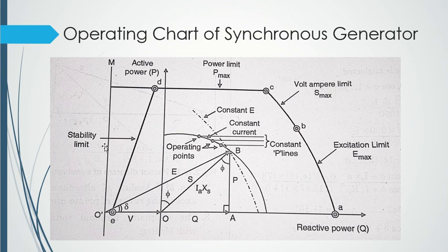But because we need some safety margin, we take the delta or load angle as 80 degrees. So in actual practice, we take a 10% margin for practical stability. Hence my DE is slanted here. See, it is not vertically perpendicular to my O dash O.